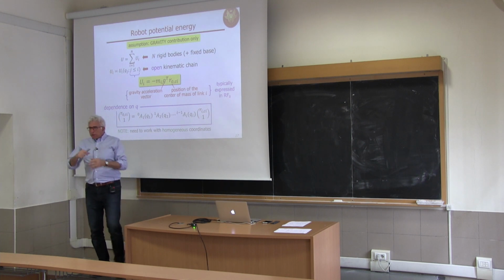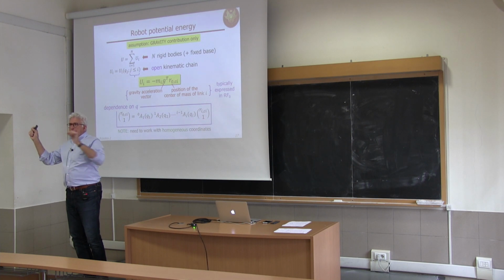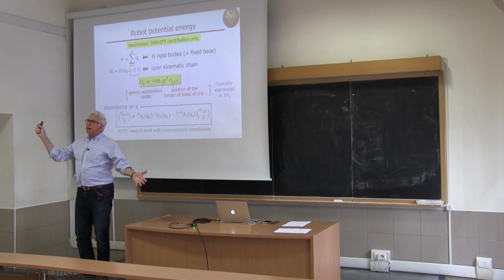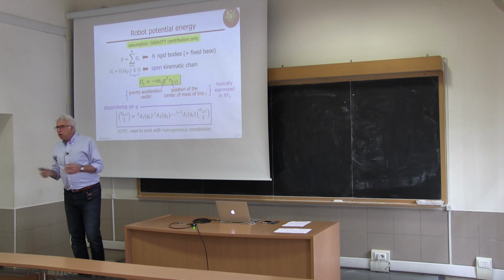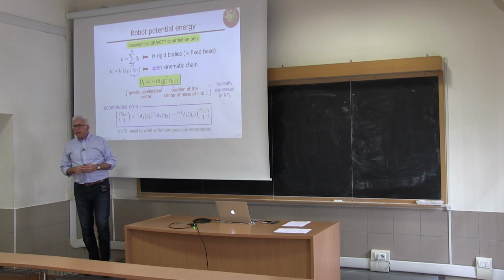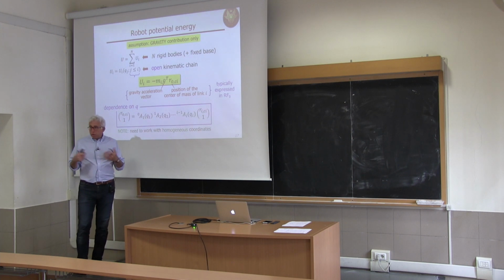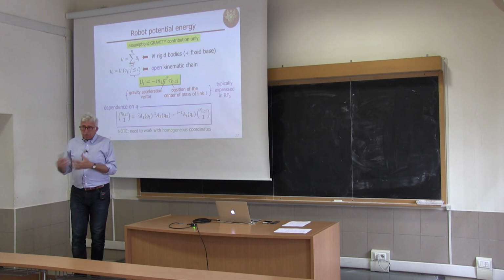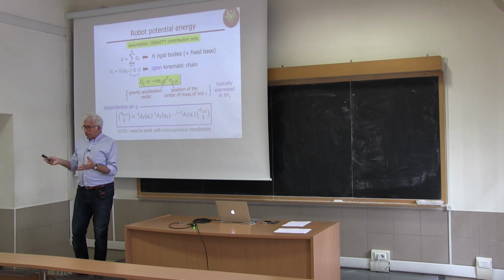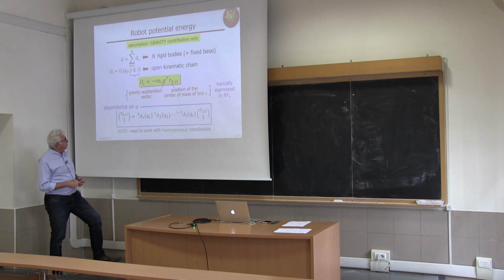And now, to transform a vector going from one origin to the center of mass into another origin to the center of mass, and changing also its frame of representation, we need to use homogeneous coordinates and the homogeneous transformation matrices A_{i-1}^i, which we have introduced in the Denavit-Hartenberg convention. So you see that the kinematic part should not be forgotten. Once you set up the system, you will use it for kinematics, and you will use it later on now also for dynamics.